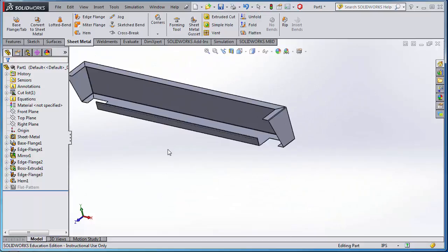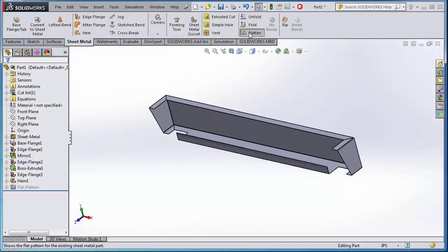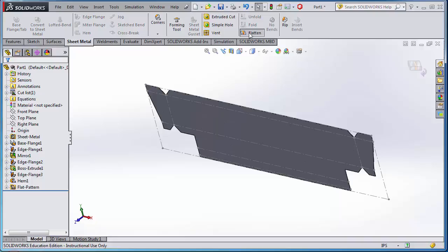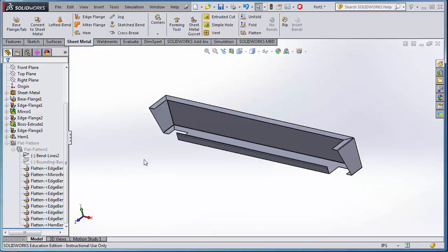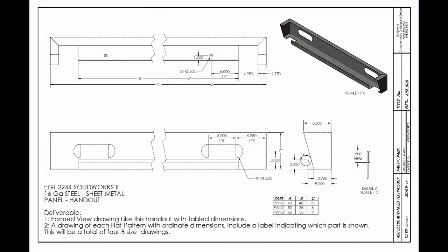All the part lacks now are the holes and slots. Use the Hole Wizard or Extrude Cut features to add those. I'll leave that for you to finish. This part is configured with 3 different sizes. Rename those changing dimensions and use a design table to drive your configurations, just like you've been doing on the previous configured parts.